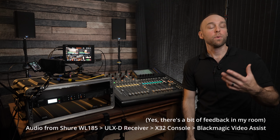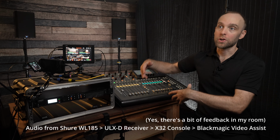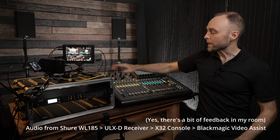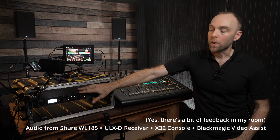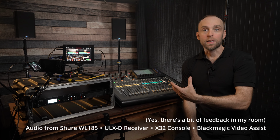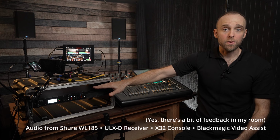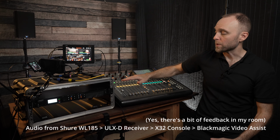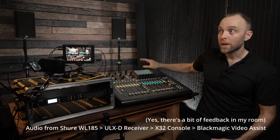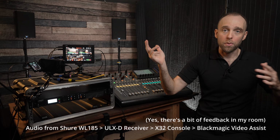There we go, and now you can hear the noisy audio that we get from having gain structured from the speaker backwards, limiting our input at the console and limiting our input at the wireless mic receiver. So the equipment's doing exactly what we've told it. We've gained low, we've kept our main audio signal near the noise floor of the receiver, and near the noise floor of the console. It gets sent out at a low level. The speakers are turned way up, so they can take this low level and amplify it, no problem.